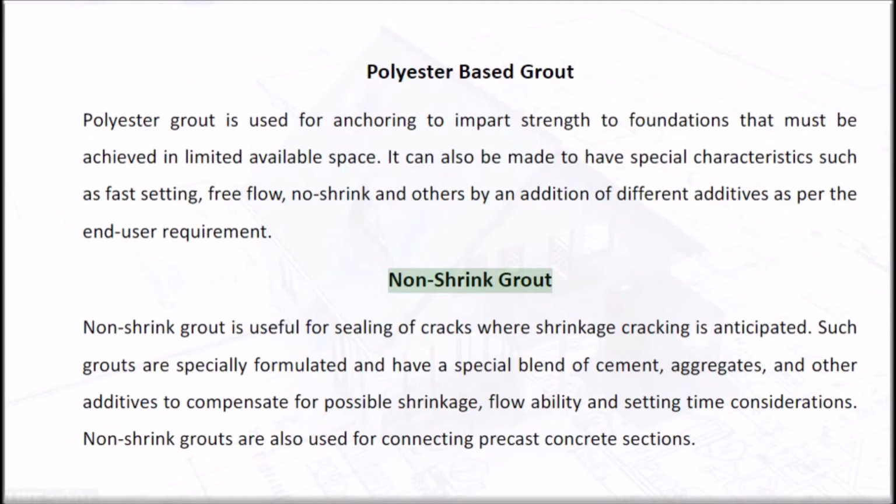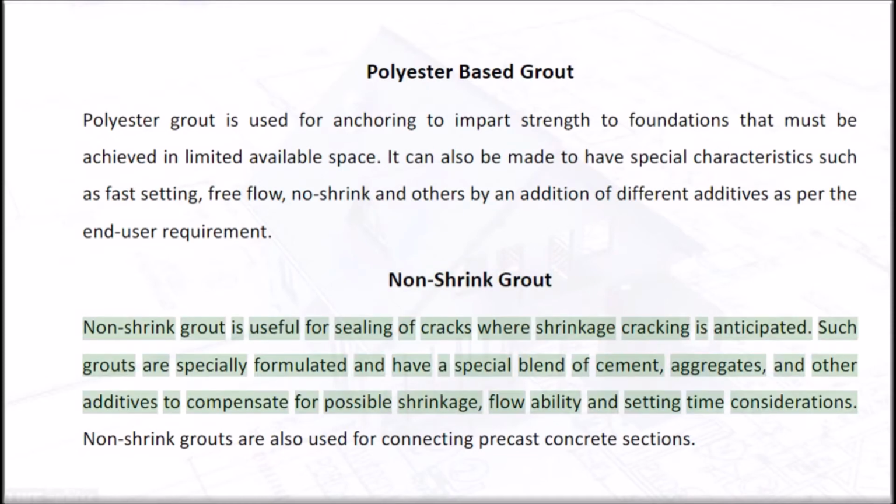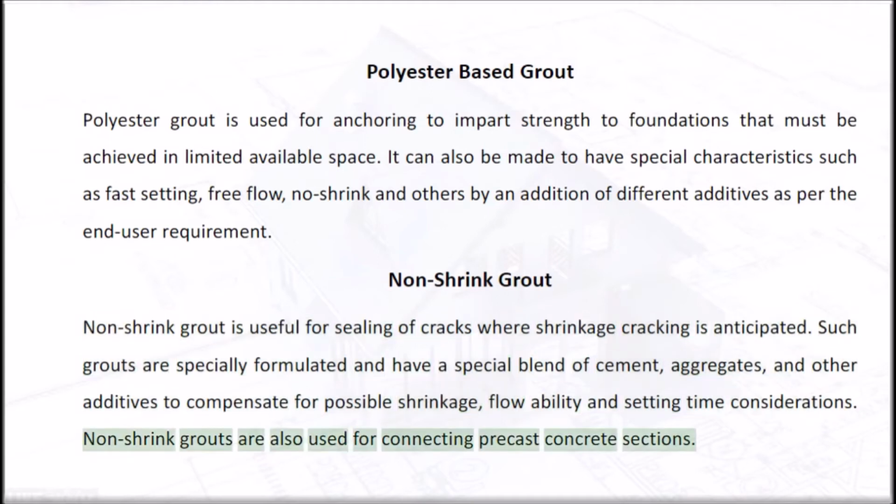Non-shrink grout. Non-shrink grout is useful for sealing of cracks where shrinkage cracking is anticipated. Such grouts are specially formulated and have a special blend of cement, aggregates, and other additives to compensate for possible shrinkage, flowability and setting time considerations. Non-shrink grouts are also used for connecting precast concrete sections.